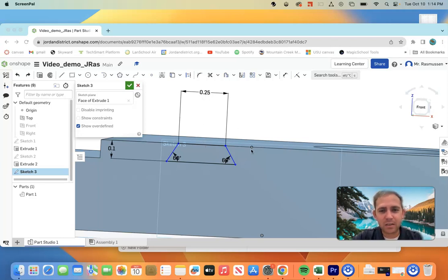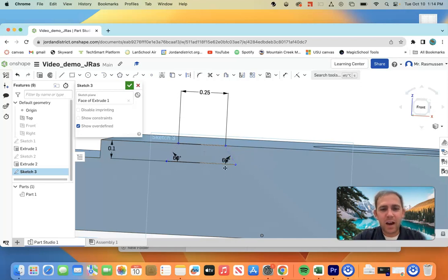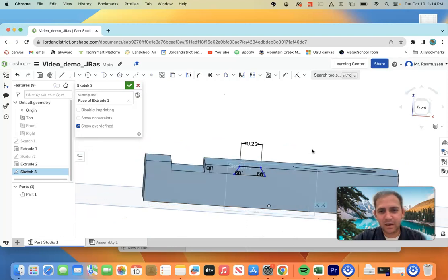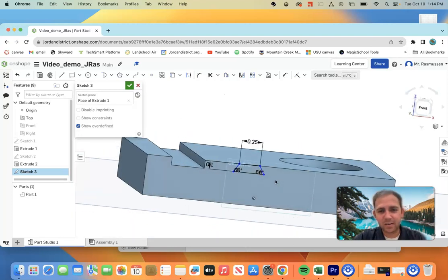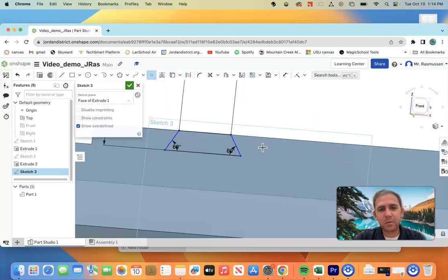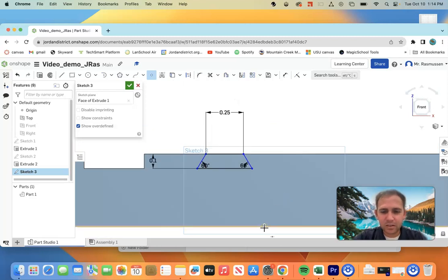Now I'm going to delete this guy because I haven't explained how to do that yet. We need to define this trapezoid to be right in the center of this whole rectangle. So let's go ahead and do that. To do that, we need a point. This point we want to be right in the center. This origin, though, I know is right in the center of this rectangle because that's how I did a center rectangle. Right here is the center.